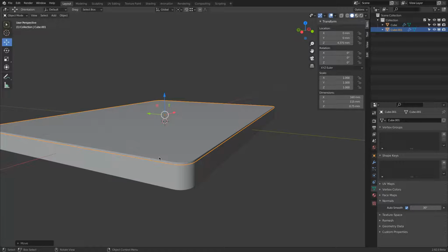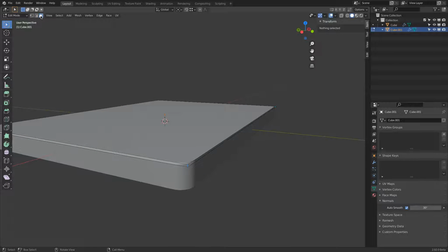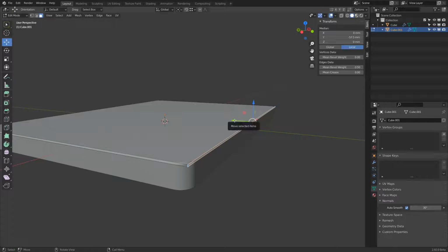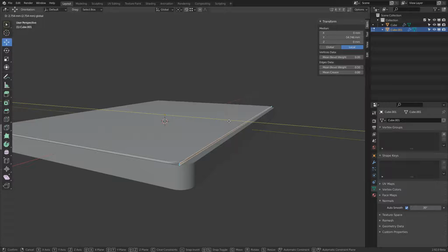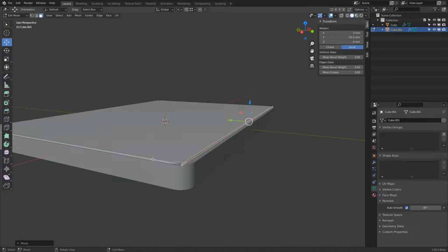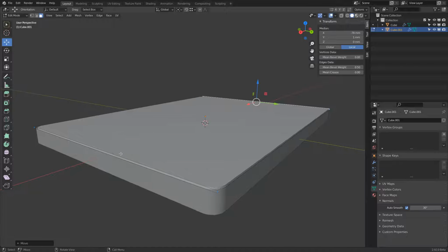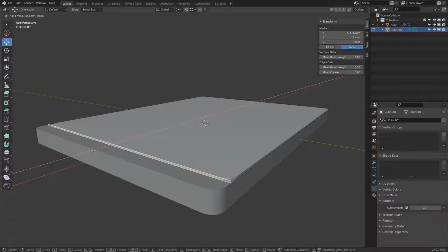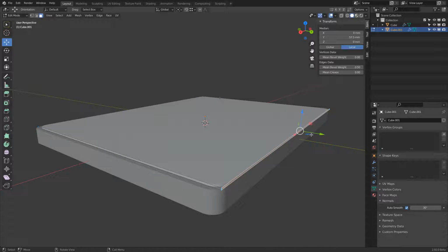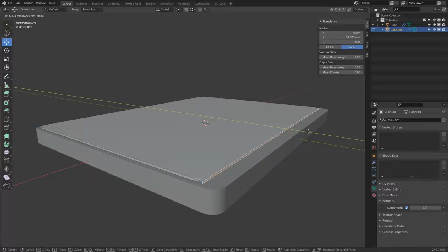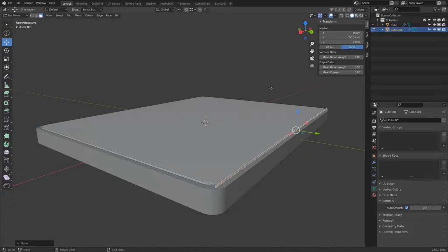This has to go in 2 millimeters each side. That is actually very easy to do. We switch to edit mode, face select, select this face, move command, drag the Y. This is, as we can see, a positive value, so I type in 2. And X, that's also positive, so just 2. Minus 2. Minus 2. There we are.